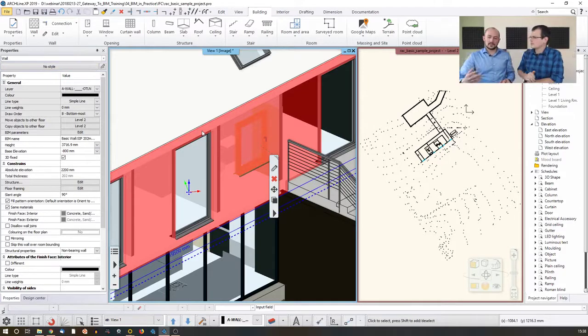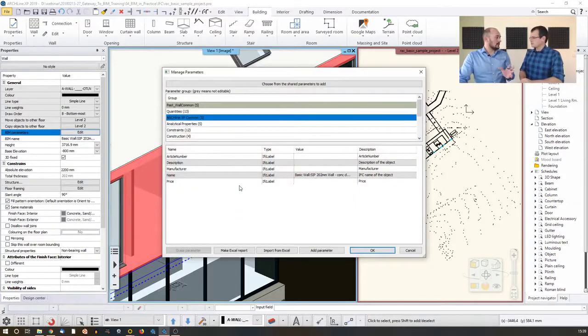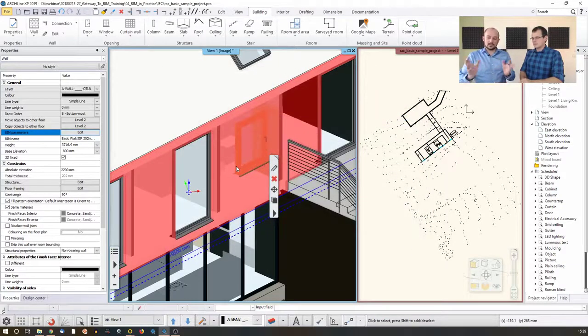In some situations, like in this specific situation, the wall was modified in the original software in a way which cannot be directly converted without losing the original shape. So in this situation, the software decides to keep the shape and allows you to decide whether you would like to keep the shape or you prefer editability. And this goes with this option. So if you anytime see a situation like this, you should go for a 3D fixed option at the left hand side. If you see that, that means the 3D was imported, it was fixed, all the BIM data came with that wall, so everything kept. But to be able to keep the consistency of this project and the original 3D, it must be saved as the 3D here.